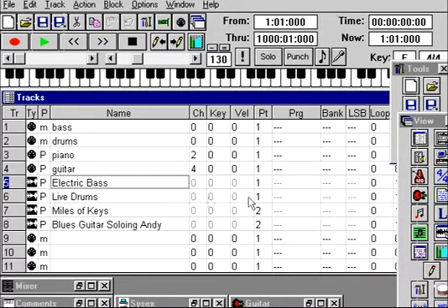And since most sound cards are usually stereo, what that means is that we can pan the bass to the left side of sound card 1 and the drums to the right side of sound card 1. And the same with the keyboard and the guitar. And that way we get 4 discrete streams of audio coming to our mixer. And depending on your setup, you may want to output those separate streams to, say, 4 different speakers and get a surround sound mix. You'd have an instrument in each speaker. Or output special signal processing, or maybe you have another effect that you want to apply just to the guitar in real time, and this allows us to do that.